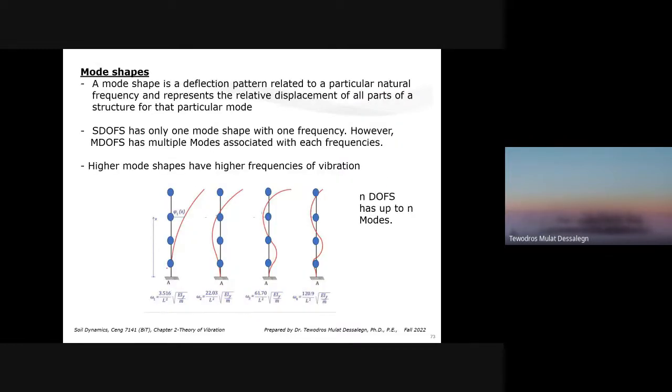Now let's see some characteristics of the dynamic behavior of some structures, like a cantilever beam. There is something called mode shapes. Last time somebody asked me how we can find the fundamental frequency of bridges or big buildings. I said, yeah, you can run modal analysis in computer programs like SAP or STAAD Pro, and they can give you that. This is exactly what they do. This is like a simple beam. Let's say it can be a pile foundation.